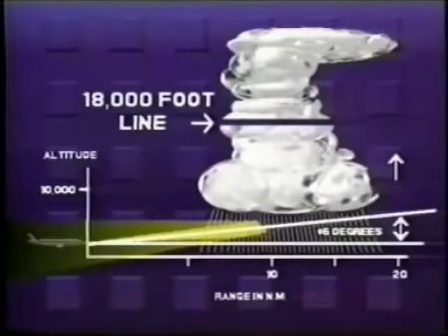On final approach, adjust tilt to 6 degrees up, using the 10 or 20 nautical mile range. This will allow the radar beam to safely scan the terminal area for weather activity, while eliminating ground returns and minimizing the radar workload.